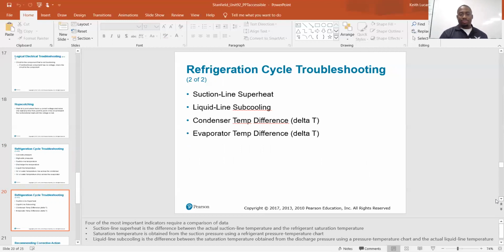Or of course, if there's no airflow across that coil, meaning either again dirty or blocked by something, or if the fan ain't turning. We talked about the 3 mass fluid flows. The refrigerant flow is one of them, and the other 2 are airflow. Airflow across the coil, the evap coil, airflow across the condenser coil. So if those ain't right, it's going to throw your pressures way off. So correct that. Make sure that's right. Make sure, at least you just look at the filter and look at the condenser coil and make sure the fans are turning before you start making judgment calls on the refrigerant.